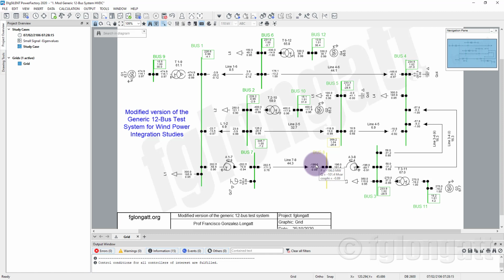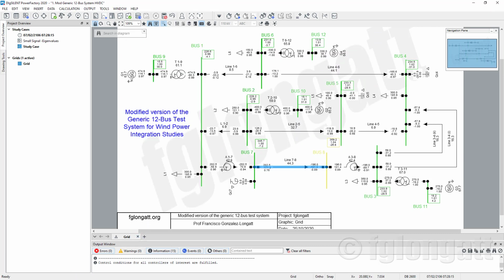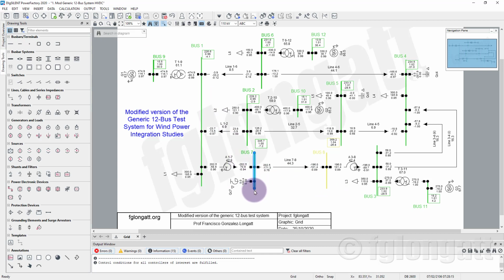Of course, this is an AC transmission line. It has resistance and reactance, and as a consequence, there are some losses over there. Specifically, you can see there are 18.8 ohms, and that is the series resistance for that system. You can run the calculations, and you can see the power that is dissipated is the difference between 202 and 196 megawatts.